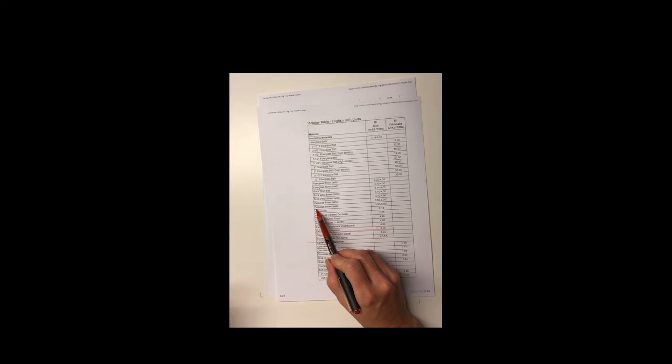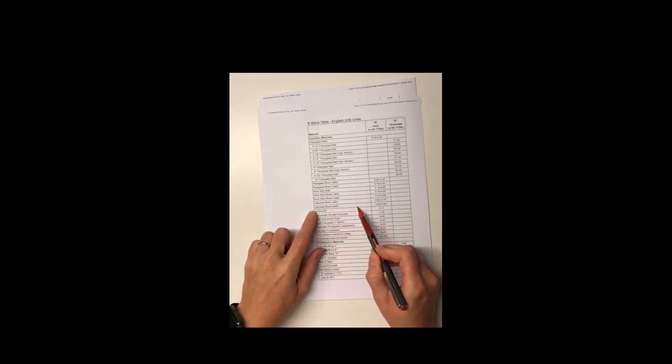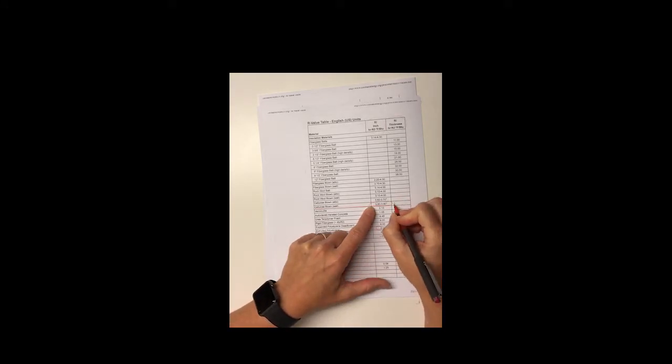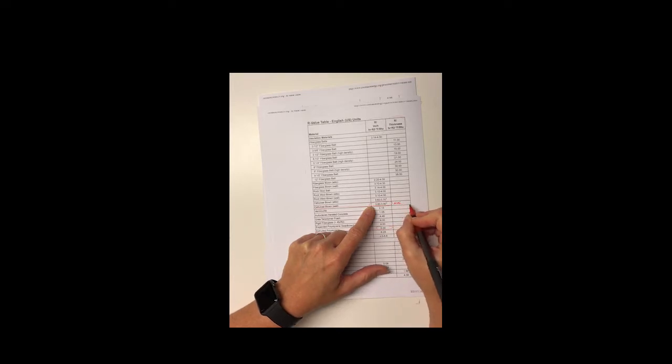So if I'm using blown cellulose insulation, you need to go back to the insulation numbers here and look at, in this case, the wall value, and it gives me a range for that. And so I need to take the average. The average for that is going to be 3.85. So in any of these you add those two numbers together and then divide by 2 in order to find the average.